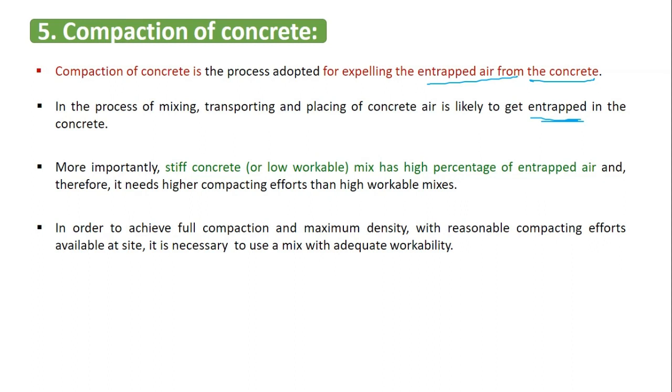More importantly, stiff concrete, or low workable concrete, has a higher percentage of entrapped air, because the water content is less, in a concrete mix in which a low water by cement ratio is adopted. When the concrete is less workable, there is a high chance of entrapped air. Of course, if it is a flowing or highly workable concrete, a lower percentage of air is going to be entrapped inside the concrete.